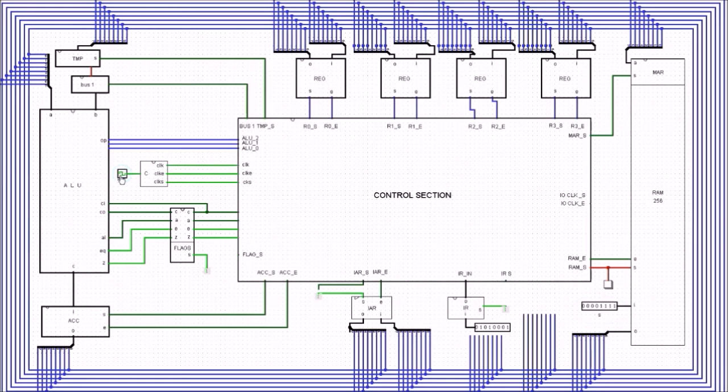Nothing will happen for the first 12. And on the 12th one, you'll see here that bus 1 goes high, because we know it's a jump if, and we know we're going to potentially be pointing not to the next place within the RAM which contains the data, we want to point to the one address beyond that, which contains the next instruction.